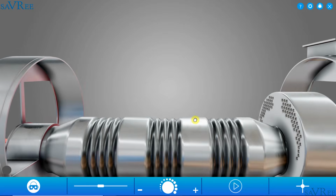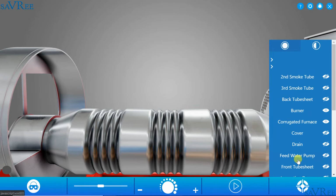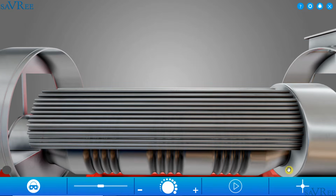So let's do that. I'm going to need to add some tubes here. This is why we call it a smoke tube boiler or fire tube boiler, because we're literally sending the smoke through tubes in the boiler. The water tube boiler, as the name implies, has tubes that are full of water, and the smoke tube boiler has tubes that are full of smoke or exhaust gas. So let's add our tubes.